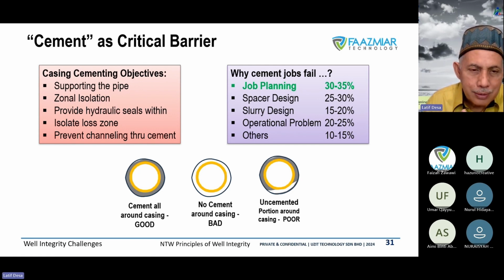But once the hole is enlarged, and the cement is rounded, you can see some cement will go perfectly around the area, but still leave a small gap between the casing and the larger OD or hole. So think about this big channeling coming up from the formation through the cement. This is the passage for the reservoir hydrocarbon hydraulically coming through the cement. You see the channeling, it starts to move up. So this is a failure of a barrier, cement in this case, causing flow to the surface.